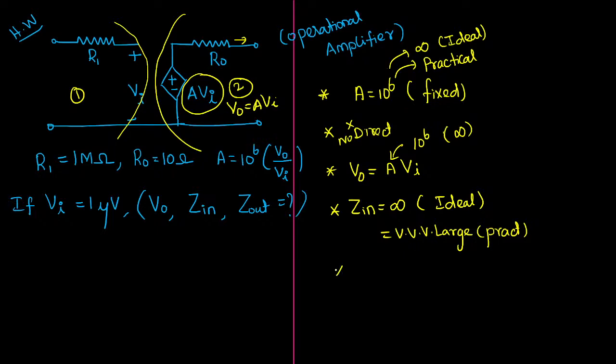Okay sir, this is input impedance. If you now observe the output impedance, when I compare input impedance with output impedance, I got only 10 ohm. Just tell me what is the difference between the input impedance and the output impedance. Can you compare them? No sir. Why? The input impedance is very, very large sir. It is approaching infinity.